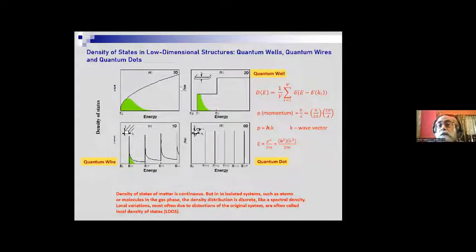And if I confine in one direction, the electron is allowed to flow in the XY plane, for example in a quantum well structure, and electron motion is restricted in the Z direction, then the density of states becomes a staircase structure. It is very important to understand how the density of states can be a staircase structure. And for the quantum wire, it's like a delta function type of nature. For a single quantum well you can have a single delta function, and if you have multiple quantum well structures, then you have multiple density of states as a function of energy, like delta function structures.